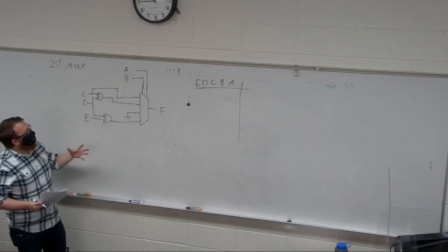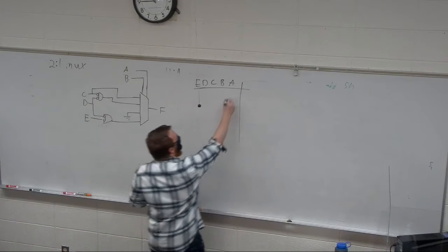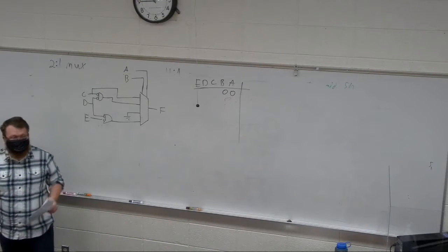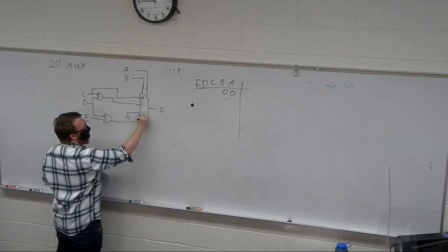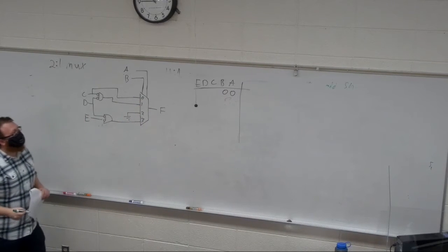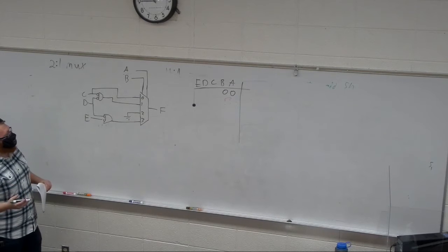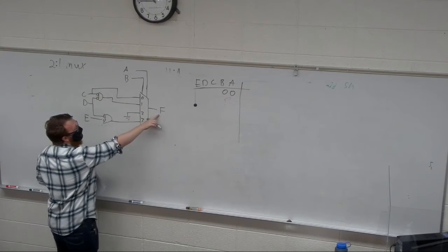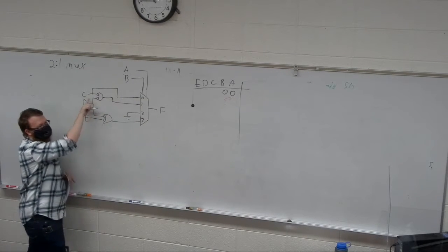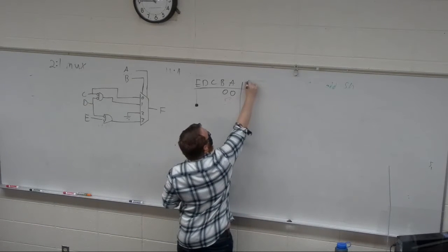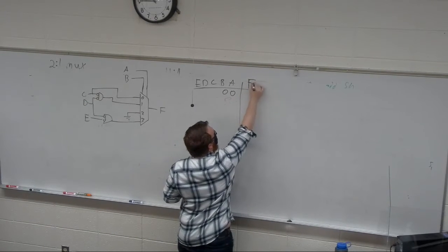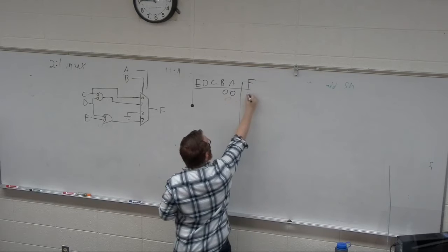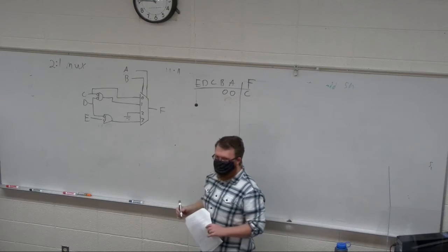And you can start going through and say, well, if A and B are 0, it selects channel 0, right? So I have channel 0, 1, 2, 3. Well, if A and B are 0, then F just takes C, right? And this is a painstaking and awfully tedious way to do this, and I will not do something this big. So F is then just C.